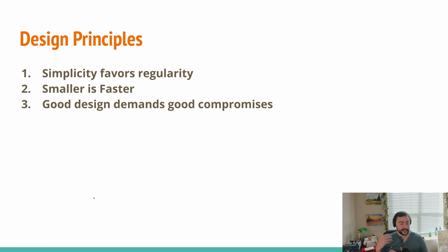So why don't we have, say, 2048 registers or 4096 registers? Well, the fact is that accessing larger structures takes a longer amount of time. So that might have negative consequences in terms of our clock rate. If we have such a large structure, we may not be able to clock our processor at as high of a frequency.